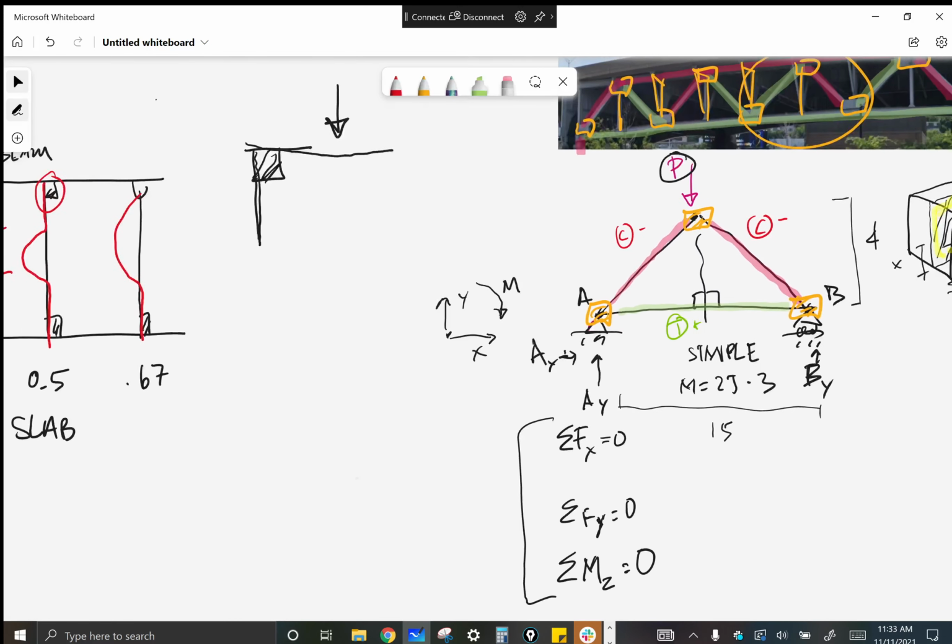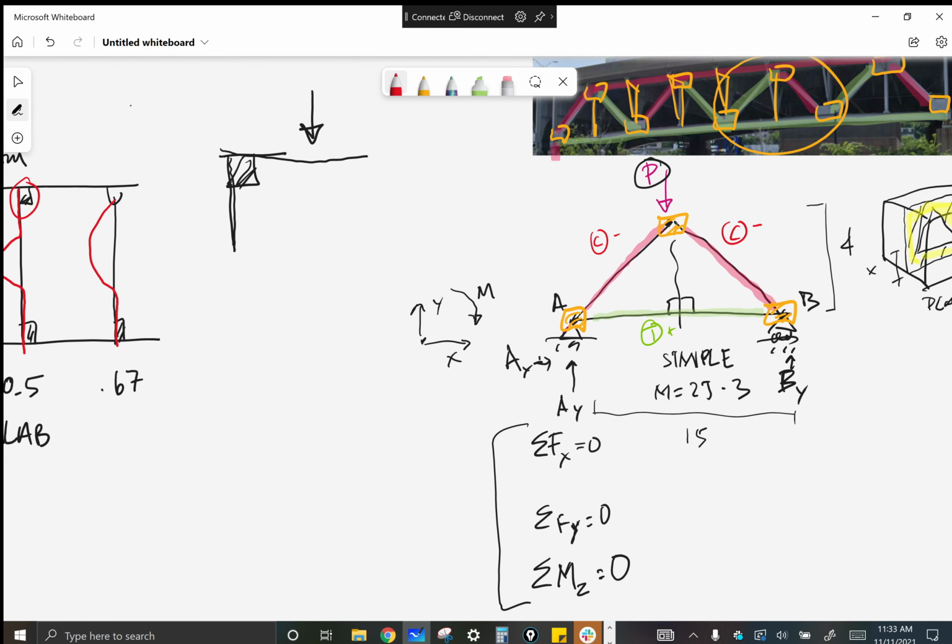So since we have no joints in a theoretical simple planar truss, I think that's where it comes from. First of all, there are two ways to go at it. It's the full length that we're dealing with, and the way we get the full length in theory is using hinged joints. Also, if we set these up to resist moment, that's called a moment frame. It's just a different theory, right? Because we're going to have different lengths that are actually available for buckling.